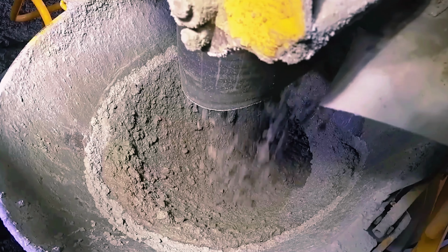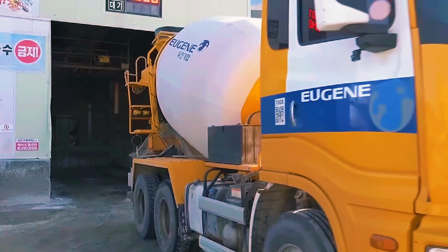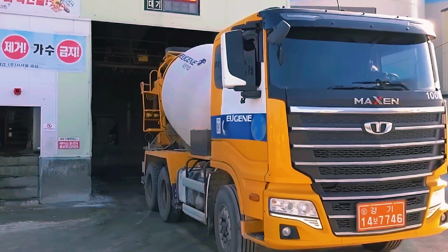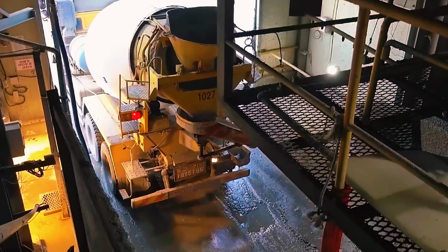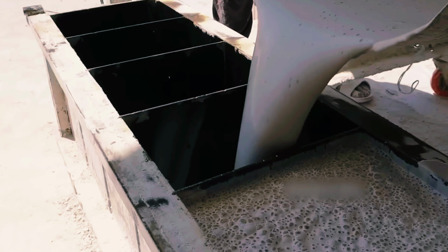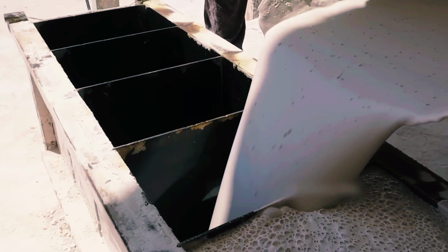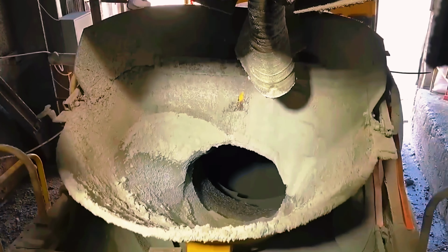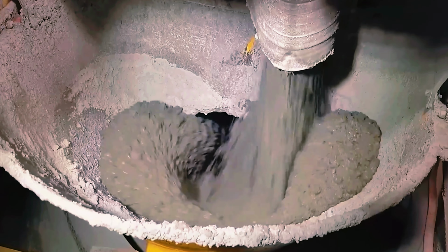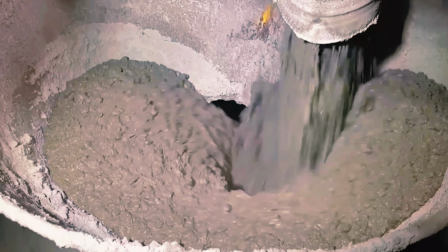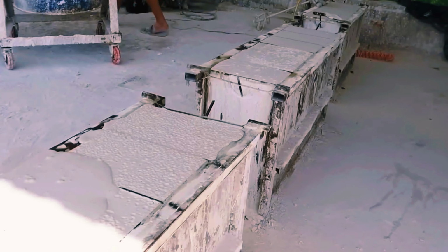During this step, it's important to check the workability of the concrete. The consistency of the concrete can be adjusted by adding more water or dry ingredients as necessary. Once the concrete is mixed and has the desired consistency, it is transported and placed in its final location. This can be done by pouring it directly into formwork molds or by using specialized equipment such as pumps or conveyors. During the placing process, it's important to avoid segregation, which is the separation of coarse aggregates from the rest of the mixture.